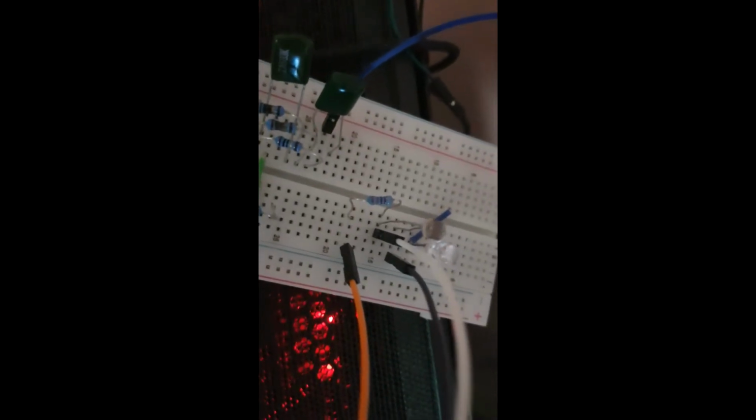Demonstration of our project, and as you can see, this is the 16x2 LCD. It's displaying the same result as the 7-segment LCD currently, and it's connected to a photoresistor. The photoresistor is connected to an 8.2 kilo ohm resistor in series, and it's connected to the Arduino, which is outputting an SPI signal to the FPGA. And we are using 4 buttons to record, reset, and for left and right navigation.